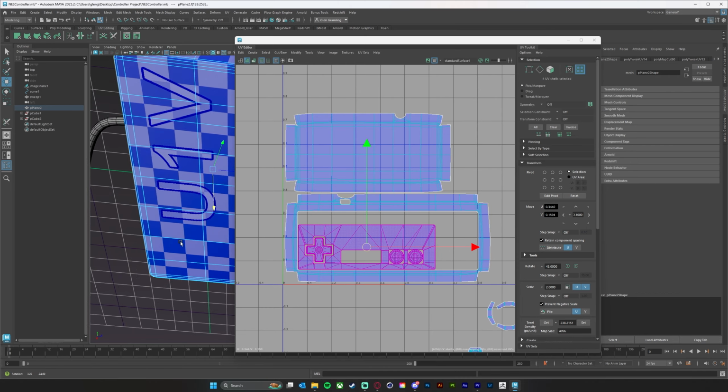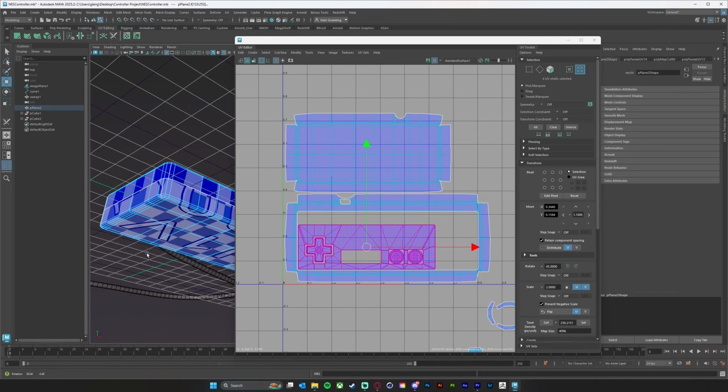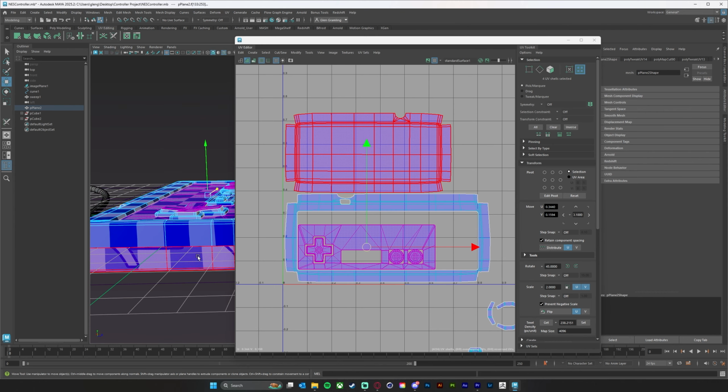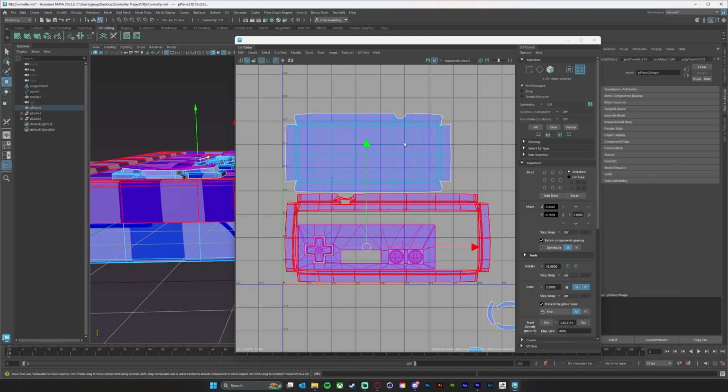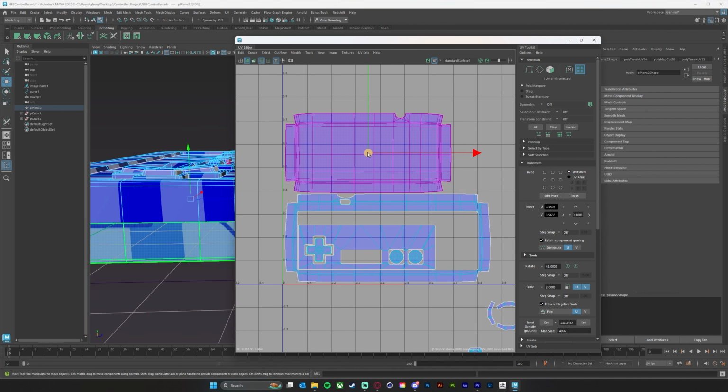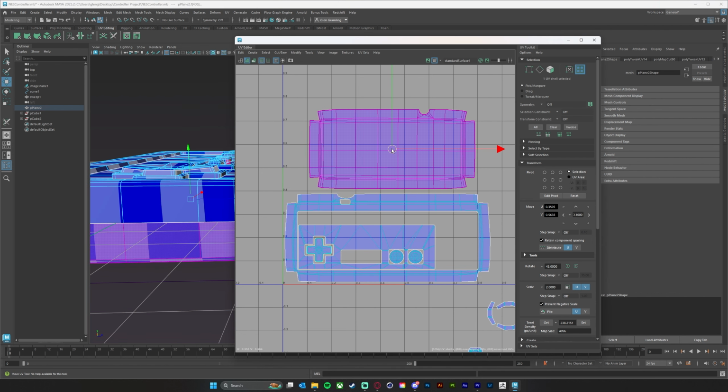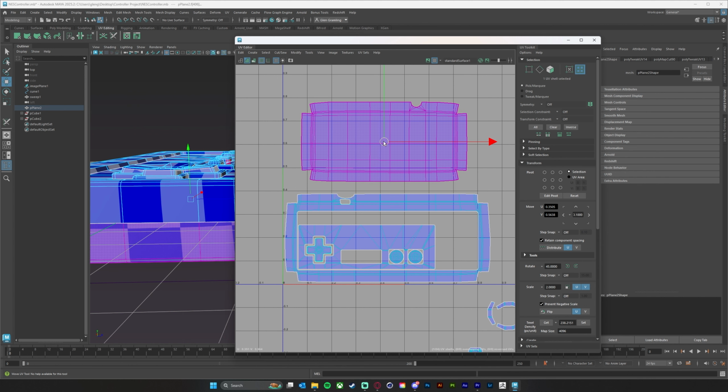Now I do notice that these are a little bit bigger around the side. So I think I'm going to need to scale this one up a little bit. Those squares are about the same size. You can see here in my 3D view where this one's a bit longer than that one. And where the seams are is where your texel density being the same is the most important, because I don't want this to be an obvious line where this is a lower resolution than that is.